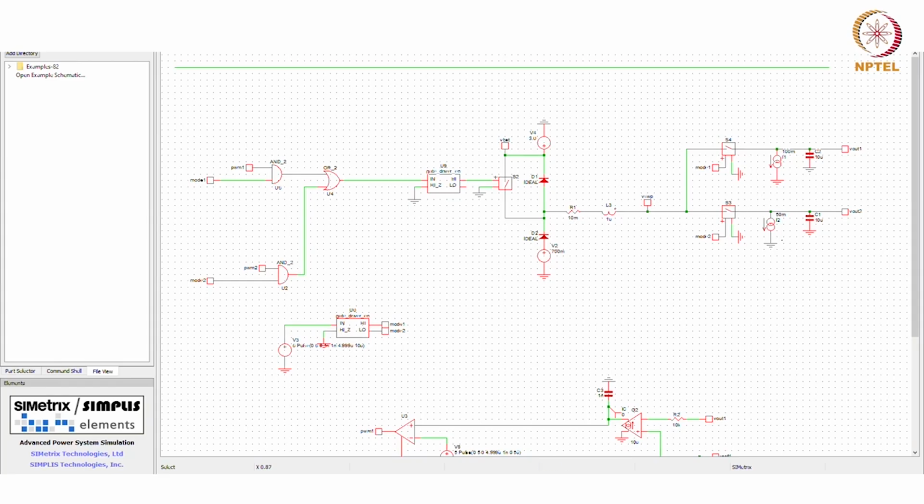So now you have to just maintain that the average inductor current in each phase is the same as what is required by the load. And if that is getting disturbed, then the extra current you have to throw out by adding a freewheeling switch. So that's why you need another third control or third time duration, which will avoid the cross regulation, and you short the inductor. In that case you are basically intentionally making the inductor current zero during that time.